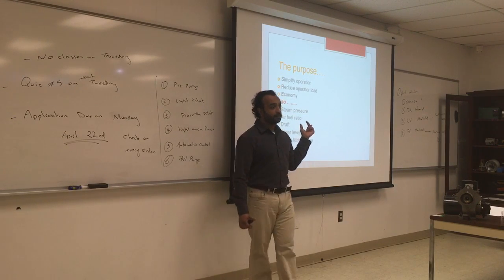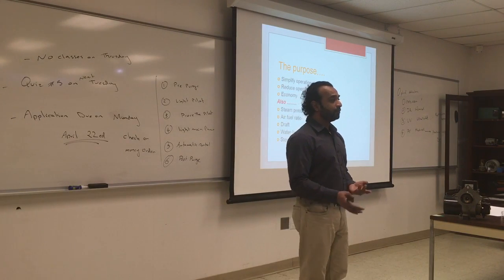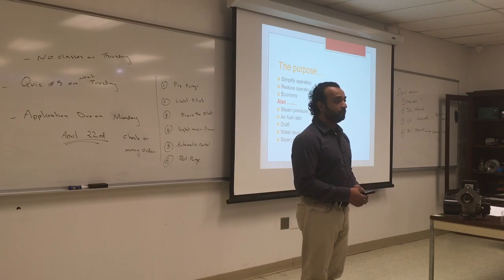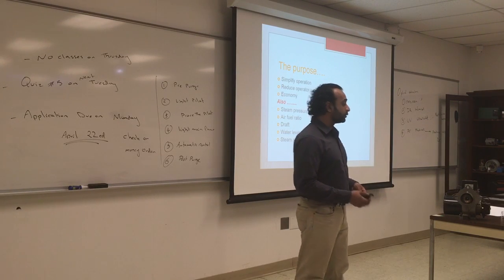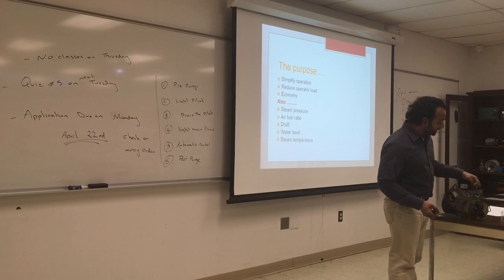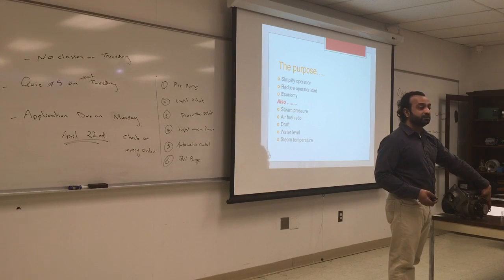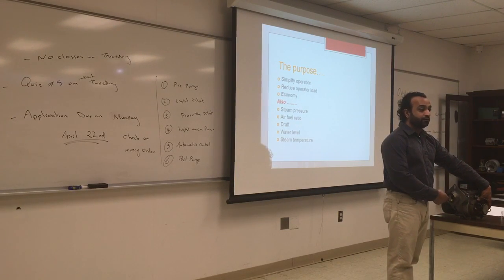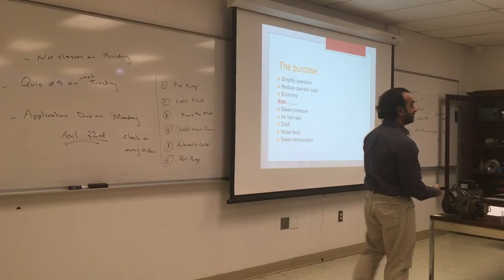So that's another thing. If you have a constant flow rate, you have to go and control the flow by hand, or open or close the damper. And that's what we did here. This kind of represents the damper, and whenever you change the fuel type, you have to change the air. And that will also give you soot. So imagine what that would be like if you had to do it many times a day. So we want something to control the fuel.